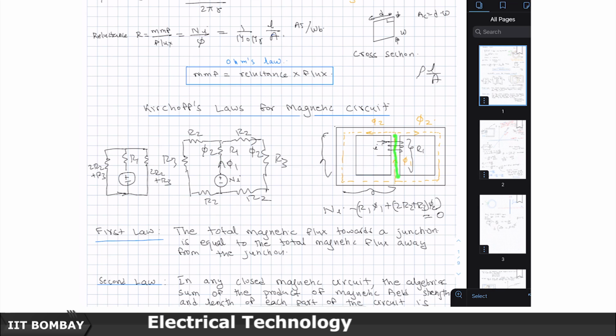So, the central part will just impose a reluctance R1 to it, then the upper side half will impose some reluctance R2, and the side limb here will impose a reluctance R3, and then finally the bottom limb will impose a reluctance of again R2 by the symmetry, and then the other part of it is moving like this. So, therefore, I have taken a symmetric construction. So, I will get again R2, R2, R2, and now what is this?